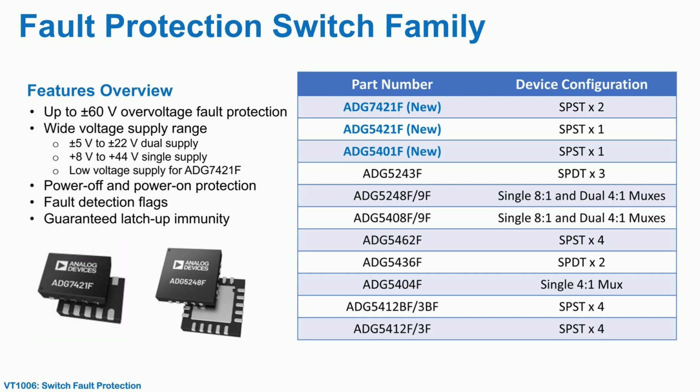There is also a low voltage option, the ADG7421F, with a supply range from ±1.8 volts to ±2.5 volts for dual supply or plus 1.8 volts to 5 volts for single supply.